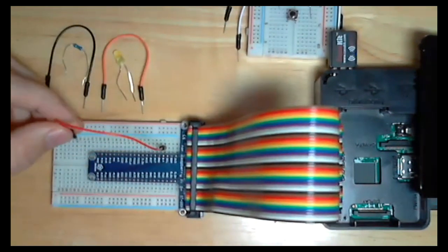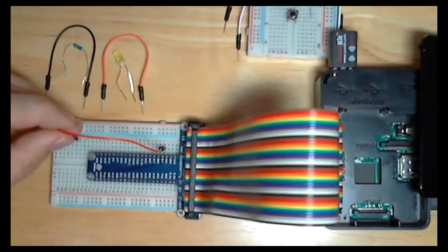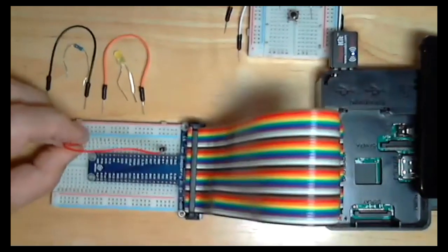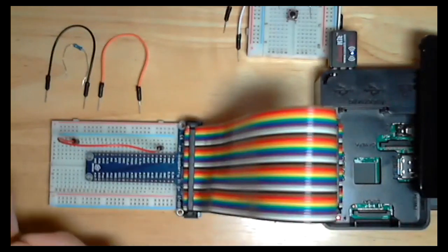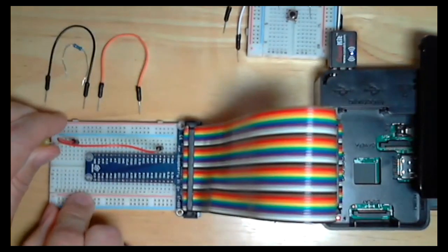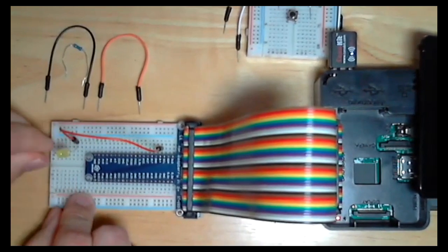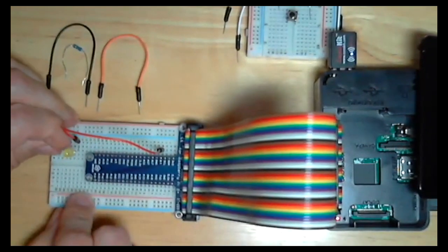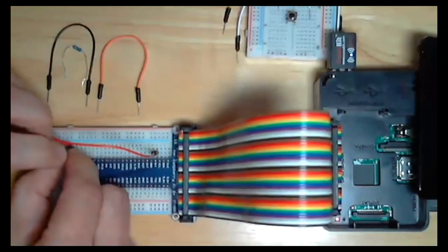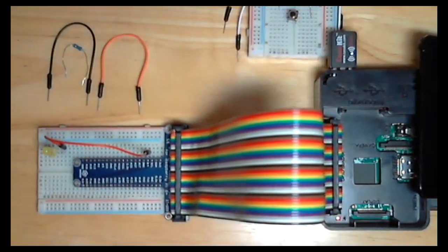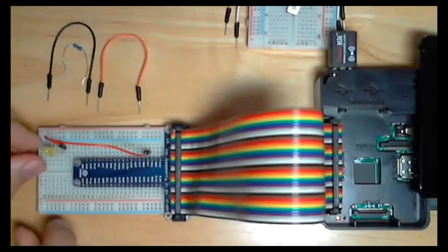So here I'm going to wire up an LED, and then we'll use Xojo code to make the LED blink. So I'm going to start by connecting it to pin number 4 here on the Pi. Grab my little LED. LEDs have one end that's longer than the other, and the longer end is the positive end, so that needs to go next to our power lead, and then we can put the other end down here, anywhere I can fit it on my tiny breadboard. I did get a bigger breadboard that's sitting off here to the side, but I haven't had a chance to switch the cobbler over to it yet.